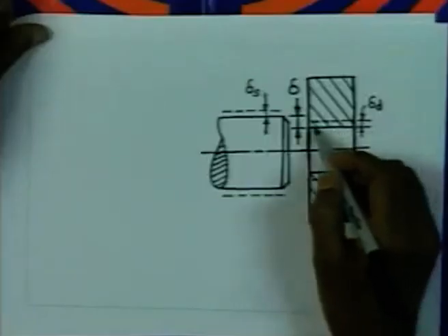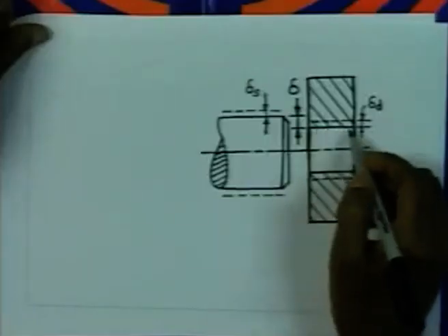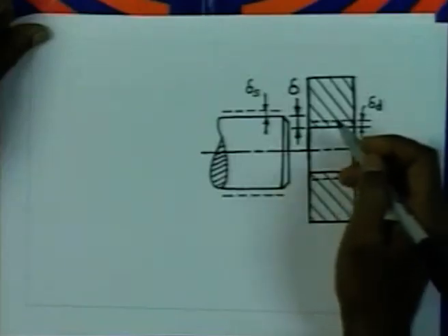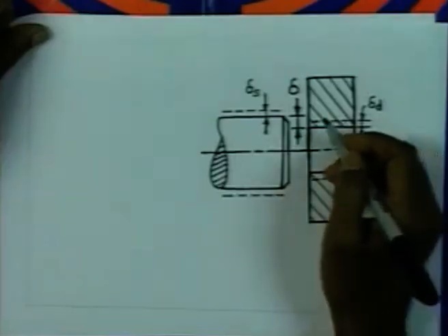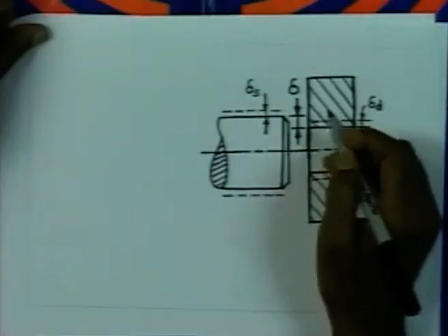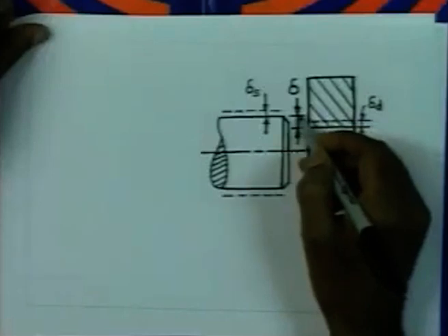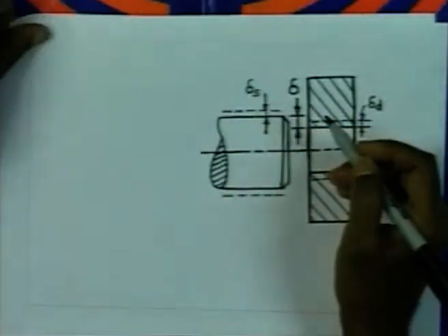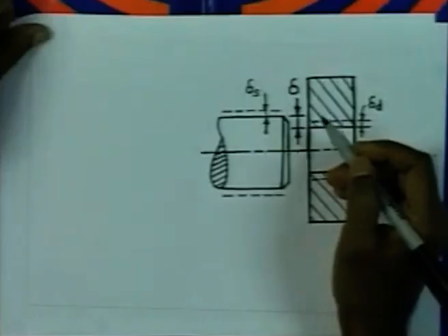If the inner radius of the disc increases such that it picks up the displacement equal to the sum of this interference plus the increase in shaft radius, then at that point it is just about to be free on the shaft.